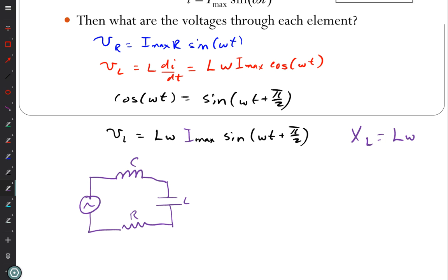an equalizer, you make a bunch of these circuits and each one has a resonance at a different point, and you put your sound signal, so now not the radio wave signal, but the sound signal, through these, and the one that has a frequency range from 100 to 200 hertz, you add that, and that's how you make an equalizer. You make different circuits that have different ranges of frequencies that they're going to allow through, and then you add up how much from each one.